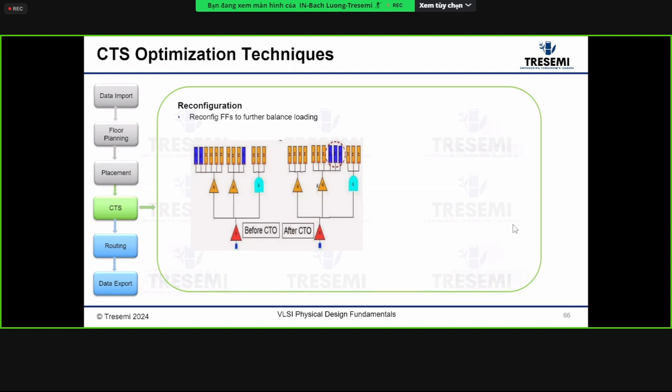So it's really not looking at a particular type of flop, other than the loading on the drivers on these branches. When it moves it, it will balance because it knows the caps and the distance on the buffer drivers. Based on that, it says, okay, if I put it here, then it balances. That's why it decided to go here. So the tool goes through its algorithm internally to figure that out. So it's not really a particular type of flop.